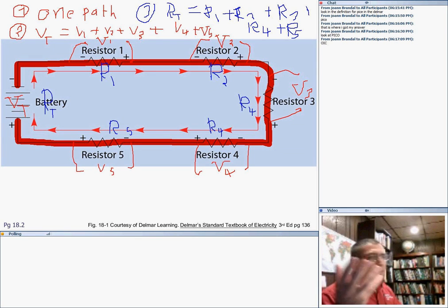But basically, an equivalent resistor is a resistor that can do the function of all other resistors. It makes sense, guys, in electronics. So if you need a 10 ohm resistor and you only have 1 ohm resistors, you can put 10 of them in series and it'll get you the equivalent of a 10 ohm resistor. So that's basically what the total resistor means. Any questions, guys?